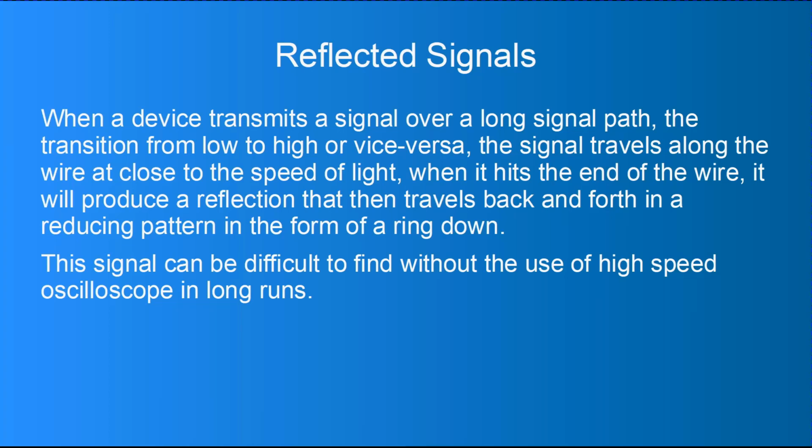It's very hard to spot these issues until you put an oscilloscope on and you can actually see it as small spikes in the wrong direction, not of the same amplitude as what you're driving the signal at. But it can cause interference with the detections.